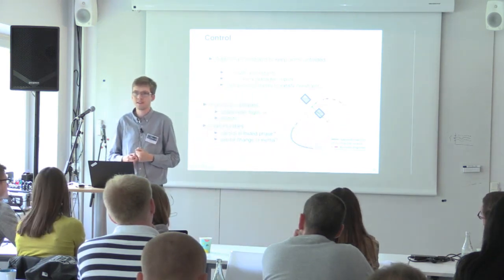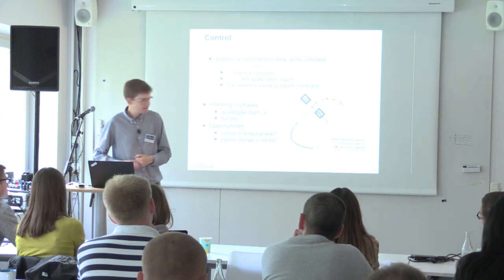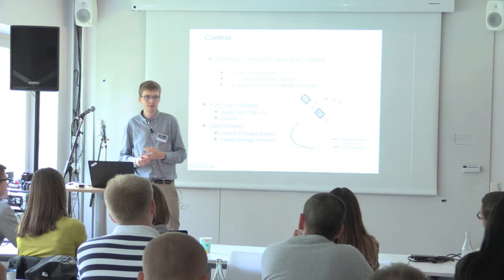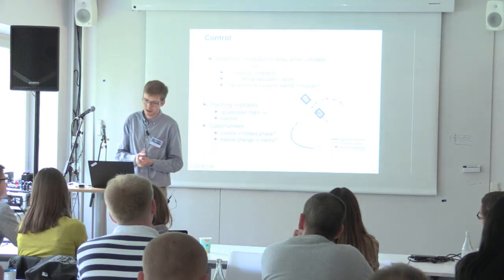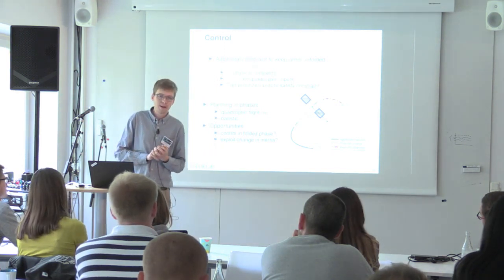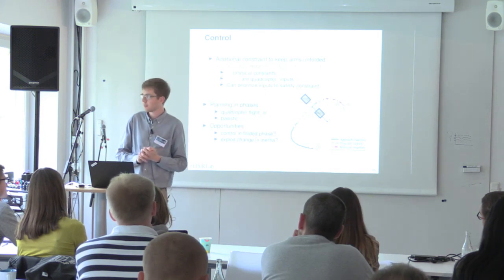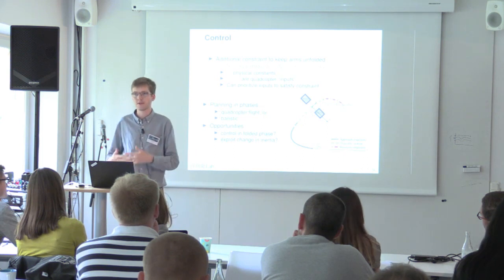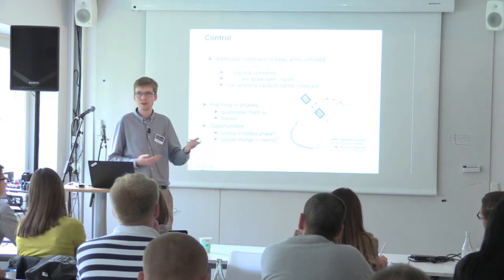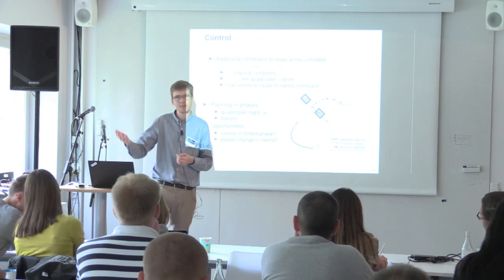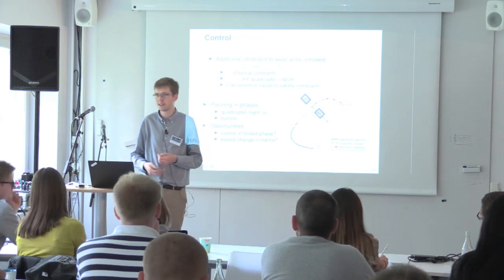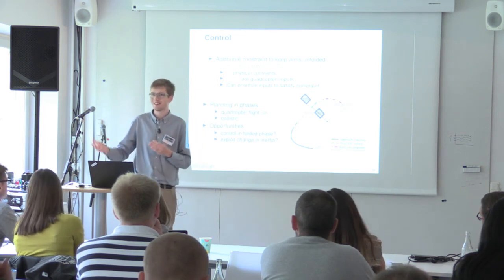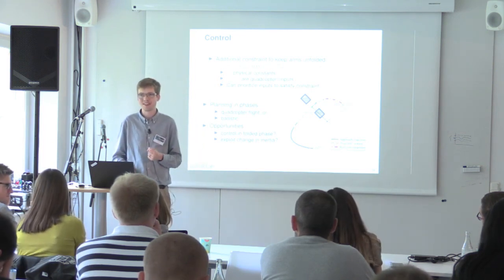Do you ever do model predictive control or anti-disturbance rejection or anything like that? Yeah, so model predictive control, we do use. The question was, do we do model predictive control and similar methods? Yes, it's a very powerful tool, especially when you deal with things that are input constrained, where you have bounded inputs, which of course you always do. The cost is slightly more complexity, more computation, etc. But honestly, in today's age, there's little reason to not do it unless you're very constrained.